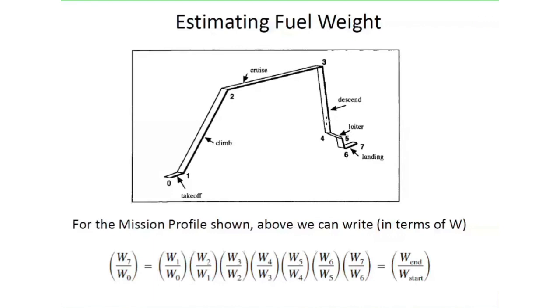So landing and takeoff are easily estimated because most aircraft have the same kind of fuel consumption in that part. And in the climb too, climb and descent will be similar. A large part of the fuel consumption in passenger aircraft will be in the cruise condition, where it is going to fly at that altitude, at that Mach number for a long time, 5 hours, 6 hours, like that. So these things will be small. So if I can plug in this W1 to W0 and 6 to 7 and all that from existing data, then I get a very good estimation of the fuel consumption.